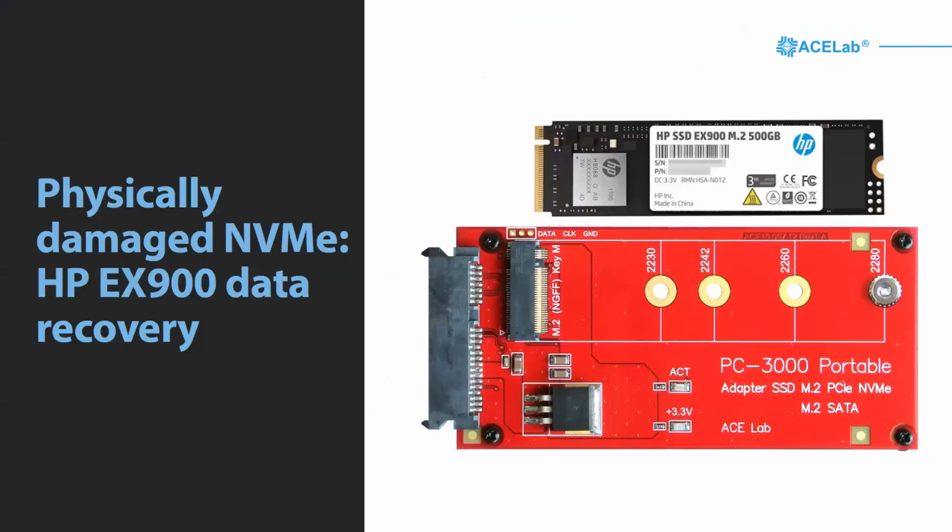But in my demonstration, I'm going to show you how we can recover the information from the HP NVMe SSD. This SSD is a brand new drive. I mean that HP company just released it a few months ago and it just appeared on the market. But anyway, right now it's supported, and with the help of the special PC-3000 NVMe adapter, it became possible to install this drive, short special points on the PCB of this drive, switch this drive into safe mode, and after that upload the loader, which will help us to diagnose the drive.